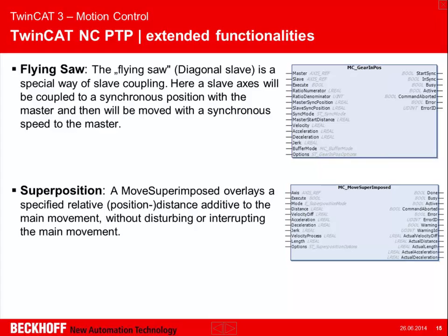Superposition is another functionality we support, and with superposition you can overlay a relative position distance additively to the main movement. This can be used especially for conveyors.